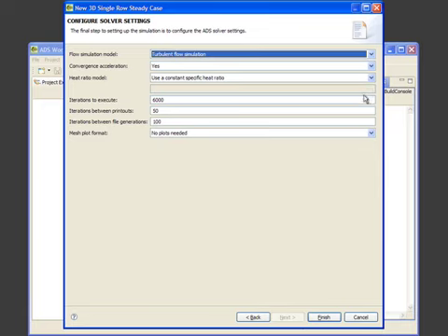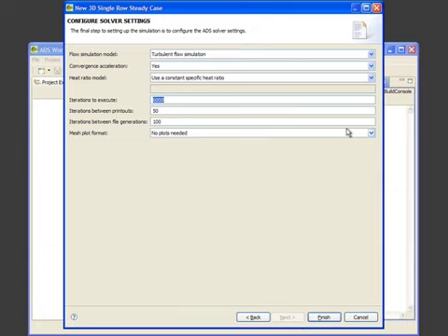The next thing to select is the number of iterations to execute. Here the default is 6,000, but really that depends on the case you are running. Some simulations come to convergence much quicker than others, and therefore it would not be worth the CPU time to execute the additional iterations. So it is best to run the simulation once, get all the performance data, see at which iteration the data converges, or when the data stops changing, and then use that to execute further simulations.